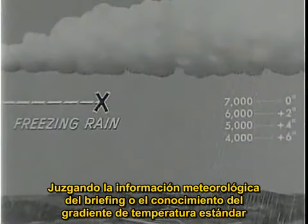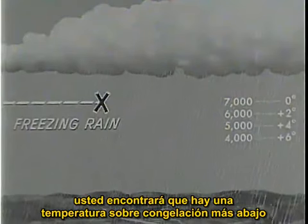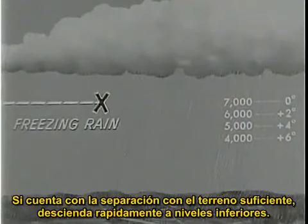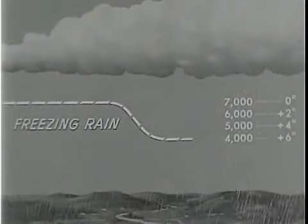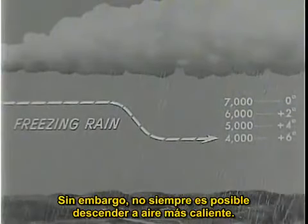Judging from the information gained in your pre-flight weather briefing and knowledge of the standard temperature lapse rate, you may find there is above freezing air below. With ample terrain clearance, descend as rapidly as possible to the lower altitude. However, descent to warmer air is not always possible.